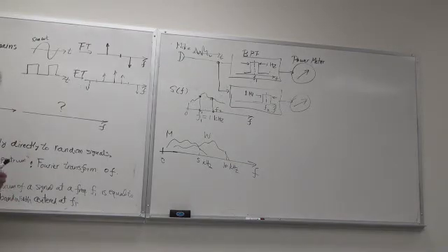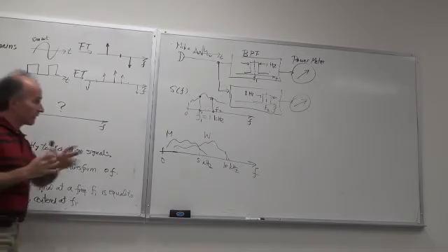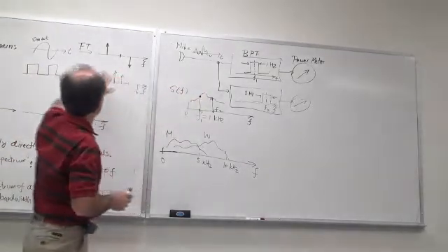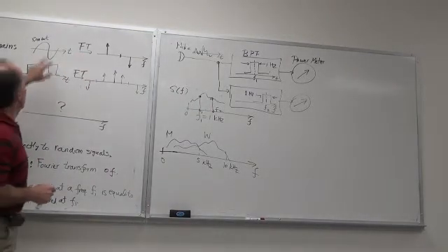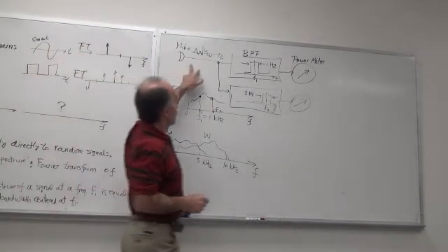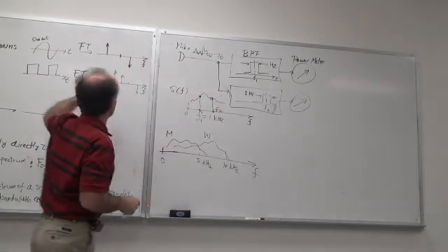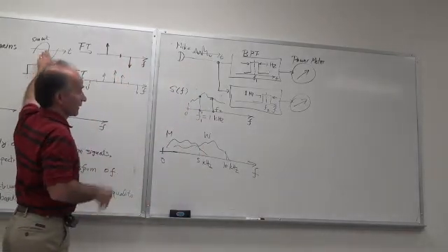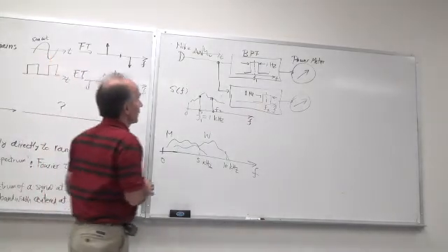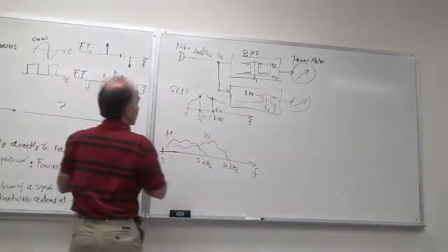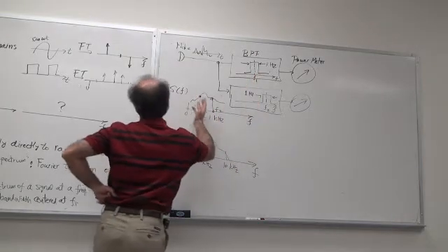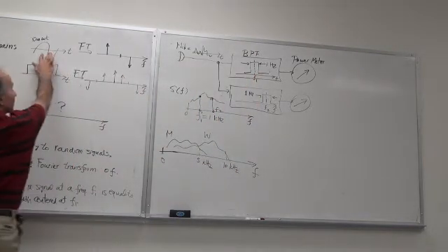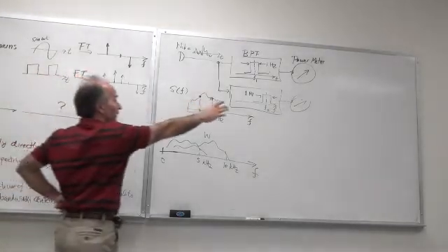For any signal, you can do that. In fact, whether the signal is periodic or random doesn't matter, because this test is more general than the simple Fourier transform that we defined before. Even if you give a sinusoid in this test, you will get the same result as before, right? Because you give a sinusoid at some frequency, let's say 1 kilohertz, right? Or let's say 5 kilohertz. You place this bandpass filter at a center of 1 kilohertz, right here. So do I have energy? No, this guy has no energy at 1 kilohertz. But at 2 kilohertz, do I have energy?